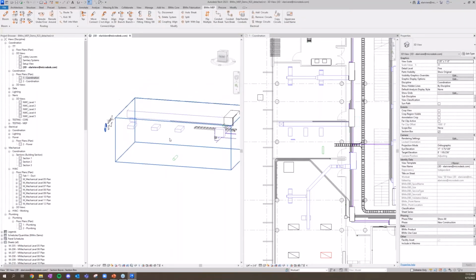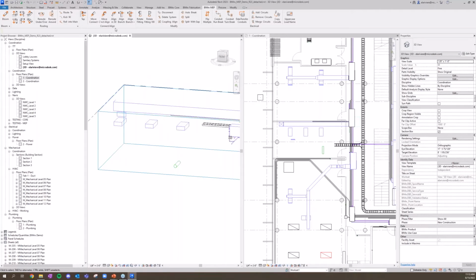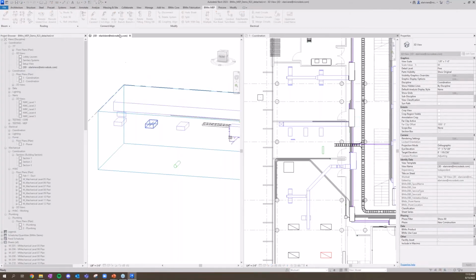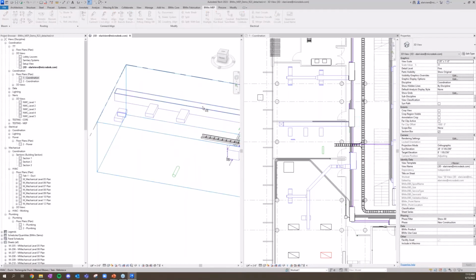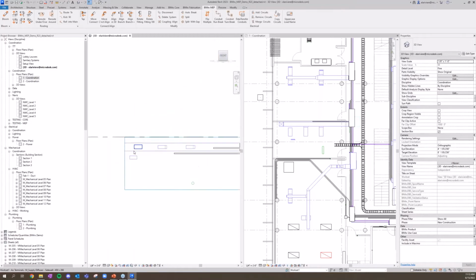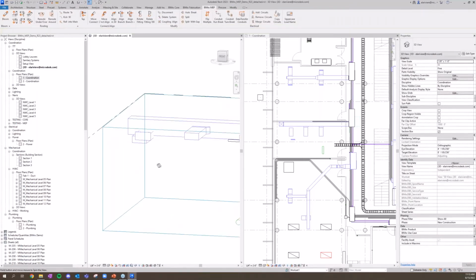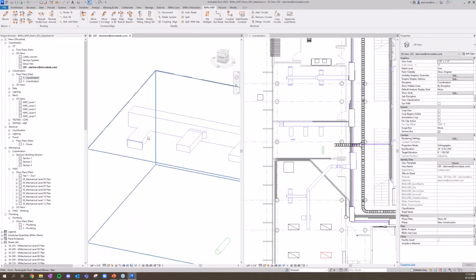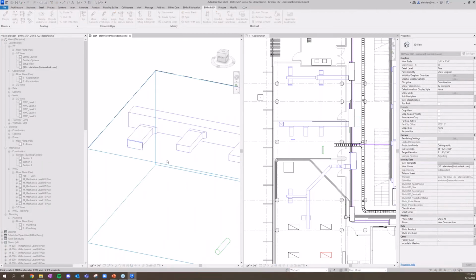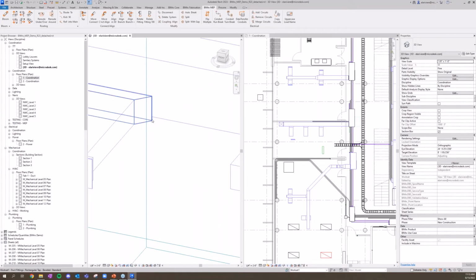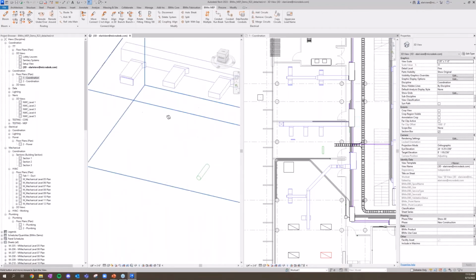So we can build in 3D incredibly easily, and we can start leveraging commands like align branch to make sure that our elements are lined up and just working perfectly. We can then leverage built-in commands to connect these things together. If we want to go back to that front view, again, you could even move these things up. And maybe I know this one is going to sit down here a little below. We could absolutely fabricate it that way, but Revit doesn't like to connect it that way. So if I want that to force connect, I can use our tap command, and it will allow that tap to connect even though it's just a little bit off the side.